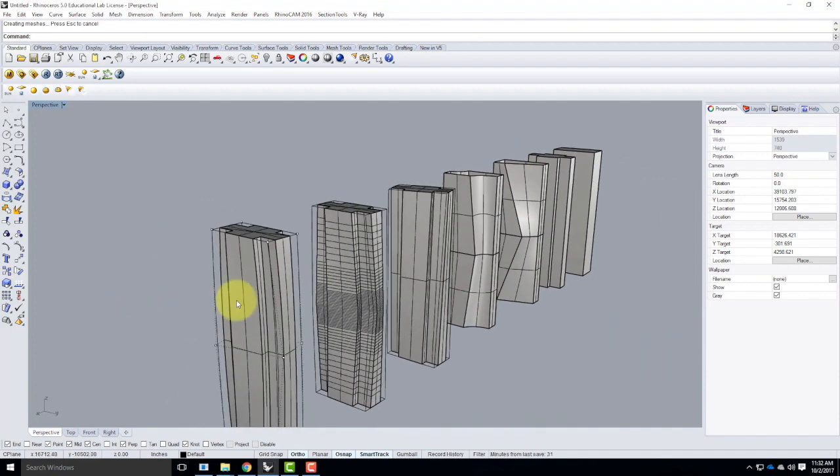I could change my degree to be 3, which gives us even more flexibility in the curve. Whenever you do that, though, you're very unlikely to be able to unroll the surface later on. So I'd stick to 2 if you can. It doesn't mean that every two-dimensional change is going to be developable or unrollable, but it's more likely to be.